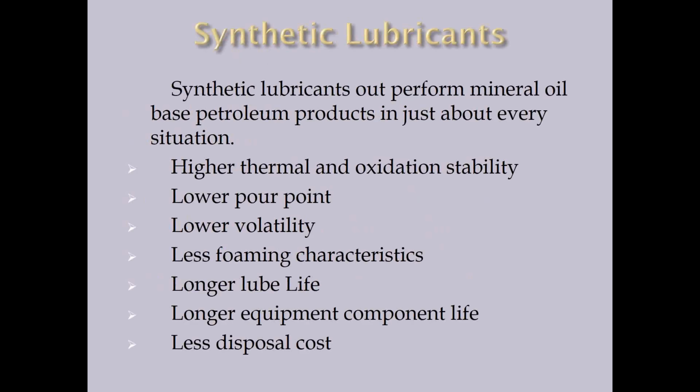Synthetic lubricants. Again, I'd say they're better in every situation. They have higher thermal oxidation stability. They have lower pour point in cold weather. Lower volatility. They're less susceptible to catch on fire. They have less foaming characteristics because they don't mix with water. They don't go through hydrolysis like petroleum lubes do when there's moisture around. The lubricant lasts 3 to 5 times longer. Longer equipment life. Most of the things that we're using synthetic lubes in, people are getting 3 to 8 times more life out of the components just switching to synthetic lubricants.